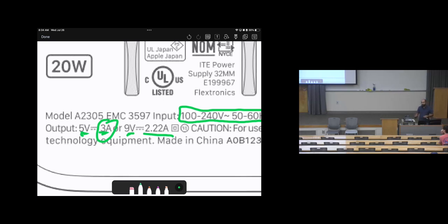So within 30 minutes, your cell phone will go from 20% to 80% during this charging cycle, because it will provide a constant current, which is 3 amperes, during all of the charging period, letting this work as a current source. After 80%, it will move to voltage control, so the voltage will be constant at 5 volts while the current will be changing. Which makes it slower after 80%.